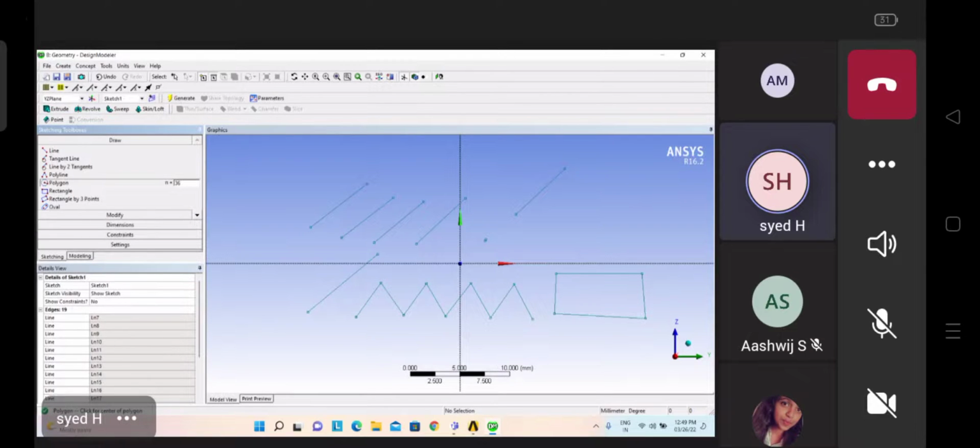So remember this. A polygon requires sides as well as a closed shape. That is the reason that to make any closed shape which has sides, we require a minimum of 3 sides. Now we can create our polygon. It's a triangle actually. Like that we can create the shapes. How many sides you want, you can enter here. For example, I want 5 sides. Enter, and it will create 5 sides here, like this.